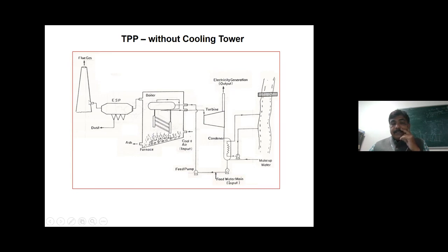Now from where is flue gas coming? So here is one unit called ESP. This is electrostatic precipitator. The outlet of this ESP is connected to this chimney. Now what is entering the ESP is the outlet of this boiler. This is actually called boiler furnace assembly. I have made it just symbolic. This need not be exactly like this. This is the furnace in which we feed coal, air. Coal burns. Here is our boiler assembly.